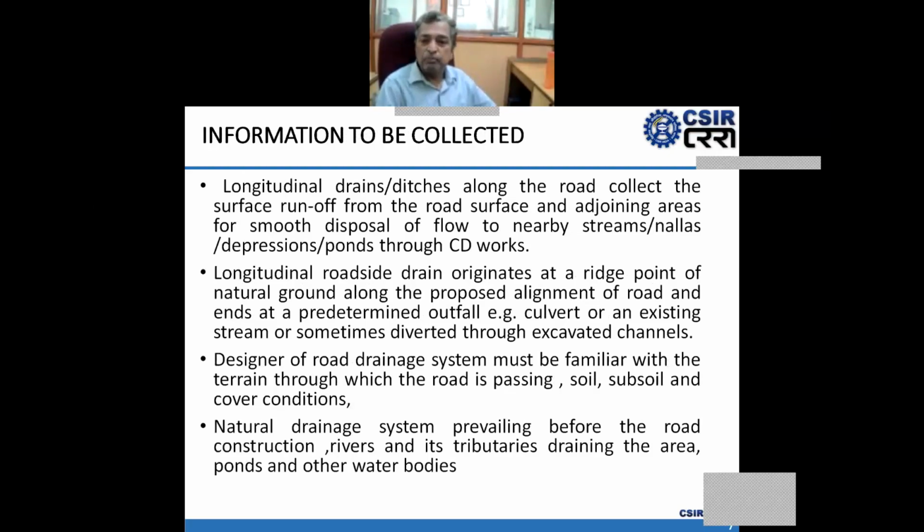This is the information that should be collected before designing the drainage system. Longitudinal drains, ditches along the road, collect the surface runoff from the road surface and adjoining areas for a smooth disposal of flow to nearby streams, rivers, nalas, depressions or ponds through cross drainage works.